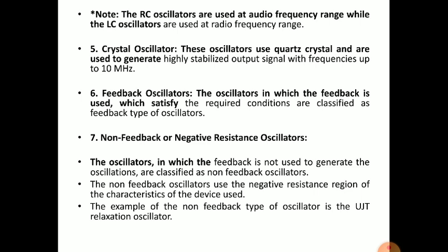What does negative resistance mean? What will happen in the negative resistance region? If we remember Ohm's law, V is equal to I R, that is V is directly proportional to I. As voltage increases, the current increases, then it is called the positive resistance region. If voltage decreases with the increase in current and vice versa, then it is called negative resistance. Yes, this type of thing can happen.